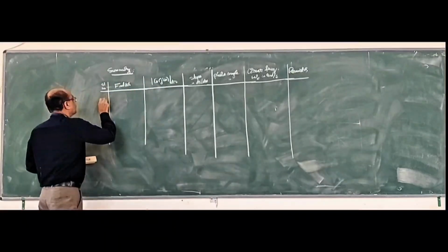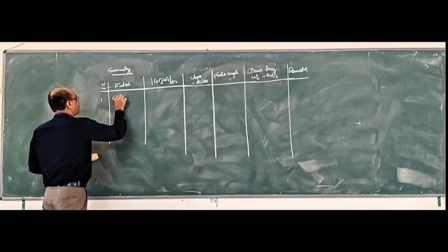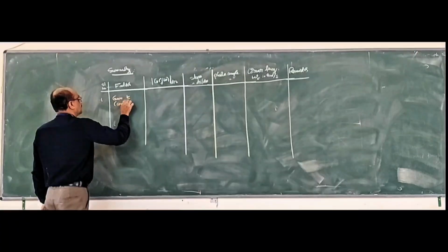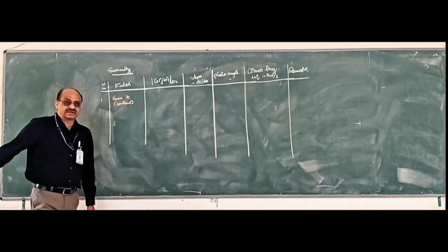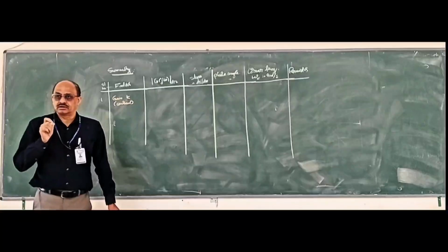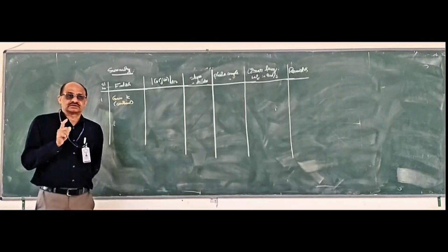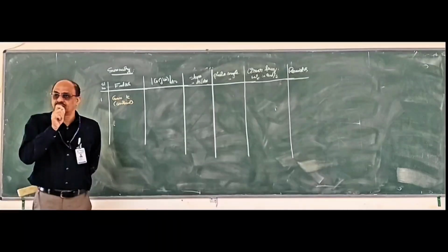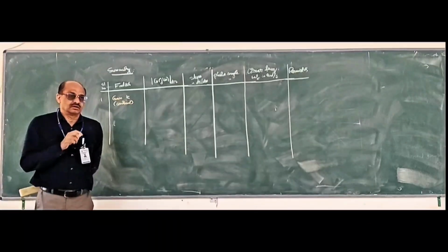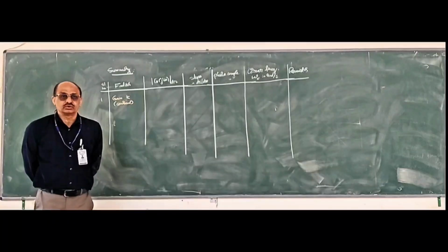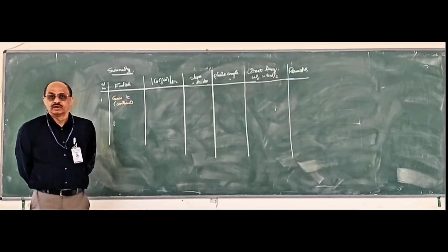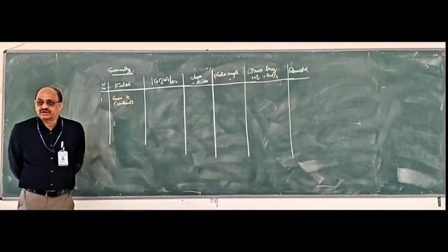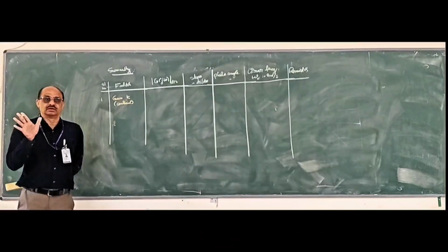Well, start with gain K. So it is nothing but a constant. How to get the gain K? After you bring the transfer function into the Bode plot form only. You should not take the gain as it is before converting that into Bode plot form. Remember, it should be considered only after you convert any transfer function into standard Bode plot form.